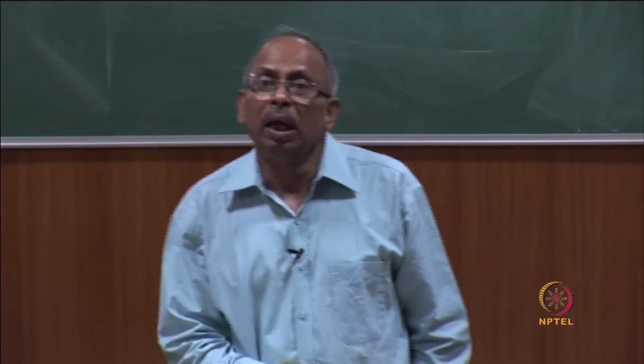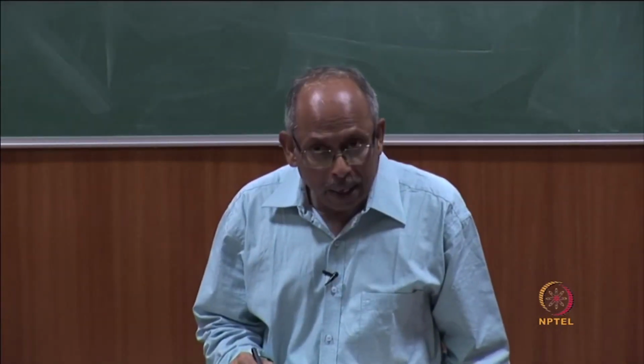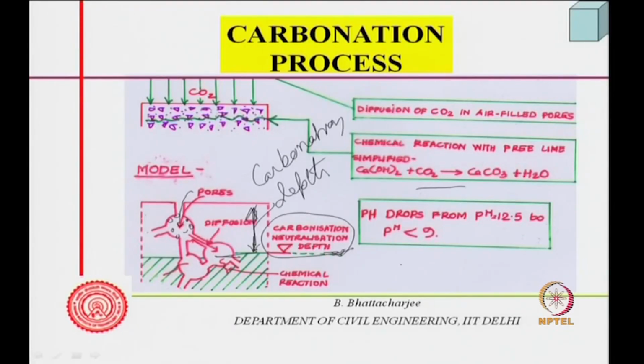In other words, carbonation is maximum at, let us say, 50 to 60% RH. At 50 to 60% RH carbonation is maximum, at 100% RH it reduces,